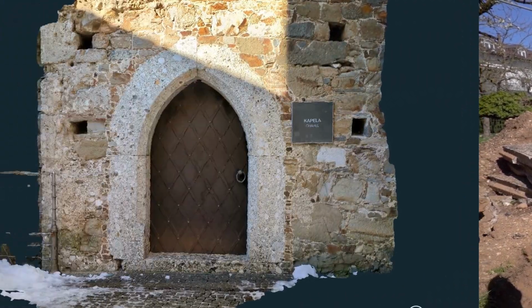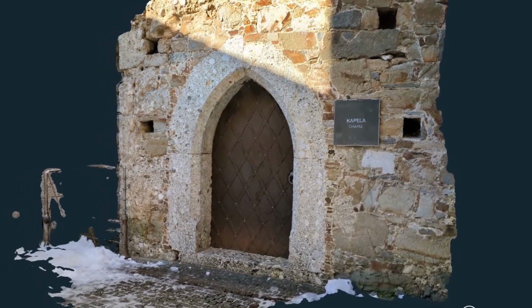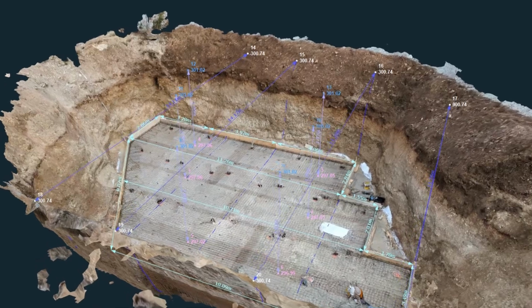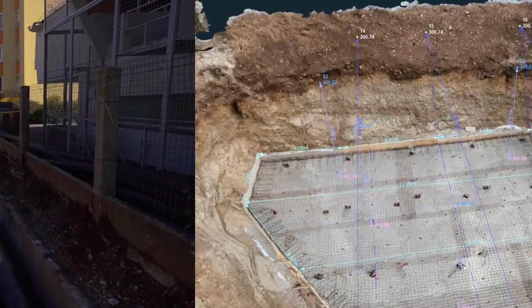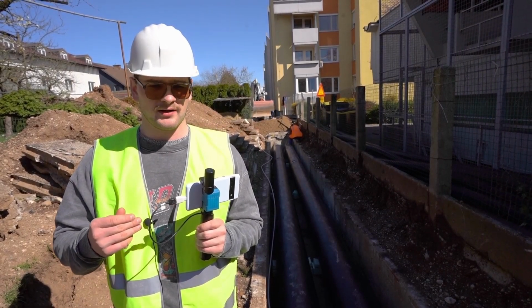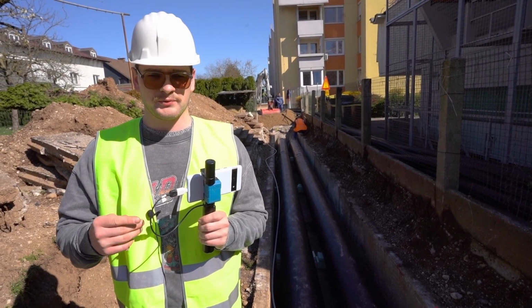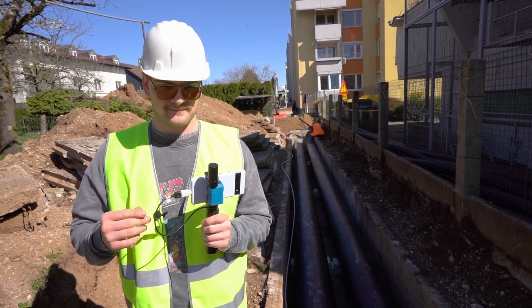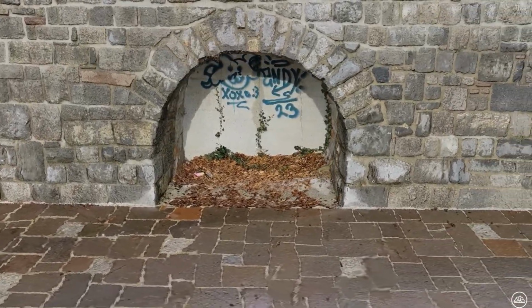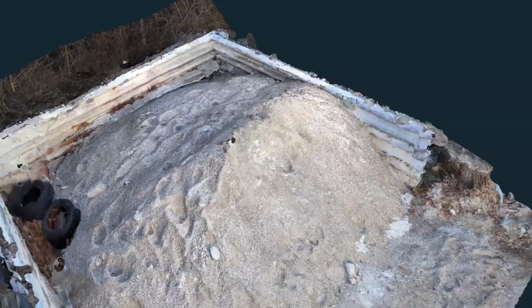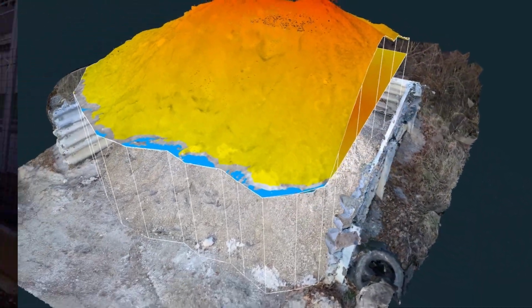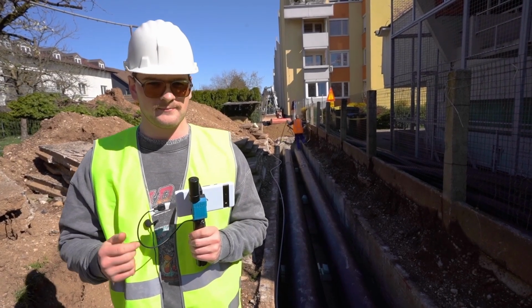We'll explore how to capture high-quality video footage with a handheld RTK device and the mobile phone, transforming it into accurate 3D models. While photogrammetry excels in capturing large open areas, videogrammetry with an RTK device is perfect for situations where drone flights are limited. This handheld approach is ideal for tasks like creating detailed documentation of complex structures and even performing volume calculations of stockpiles or buildings. Now let's set up our phone.